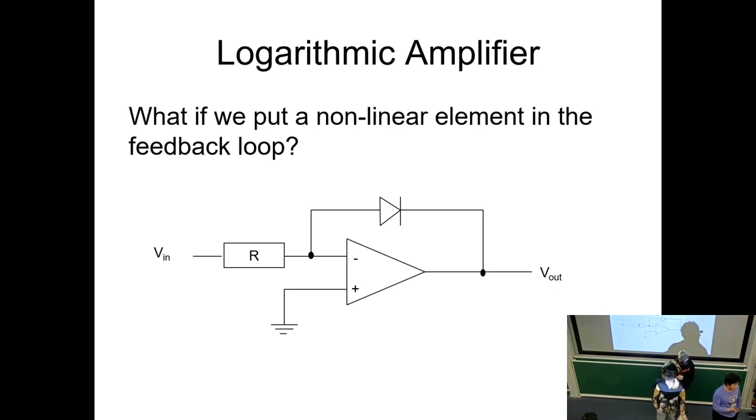But if you put a buffer in there, you've made an adder. So the op amp is just there to make it work correctly. It does things with the input and output impedance, which is very important. If you take that connection of your sum point, put it into a buffer, and draw the circuit, you'll get that adder circuit. The buffer is an op amp, and by adding these two other resistors to the buffer you've made an adder. More or less, a very simple adder.